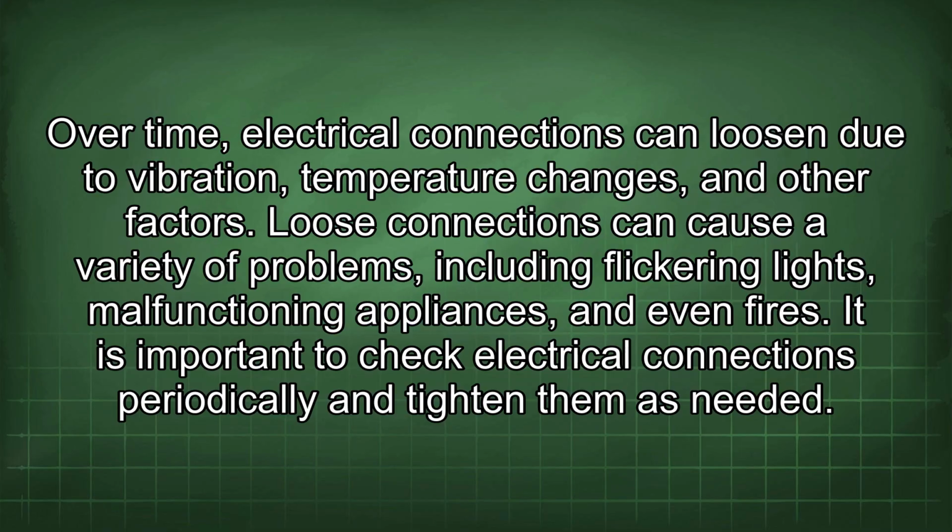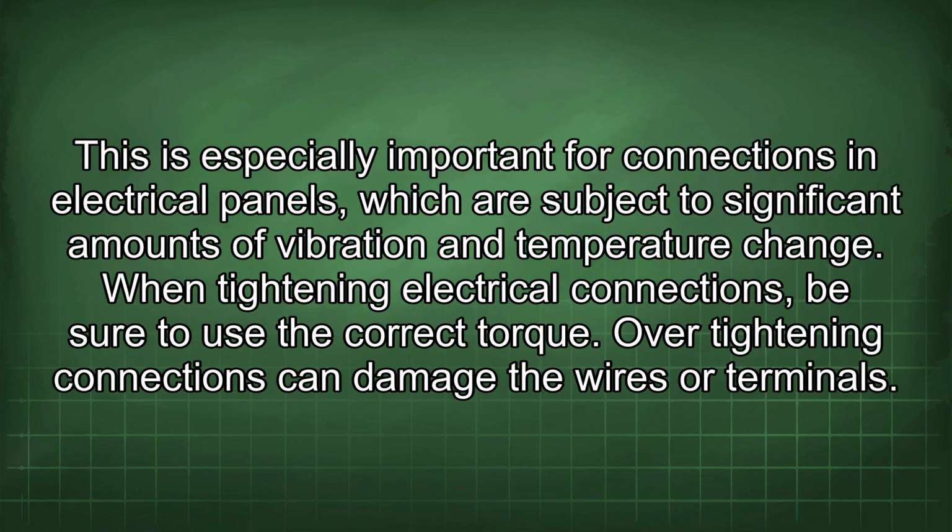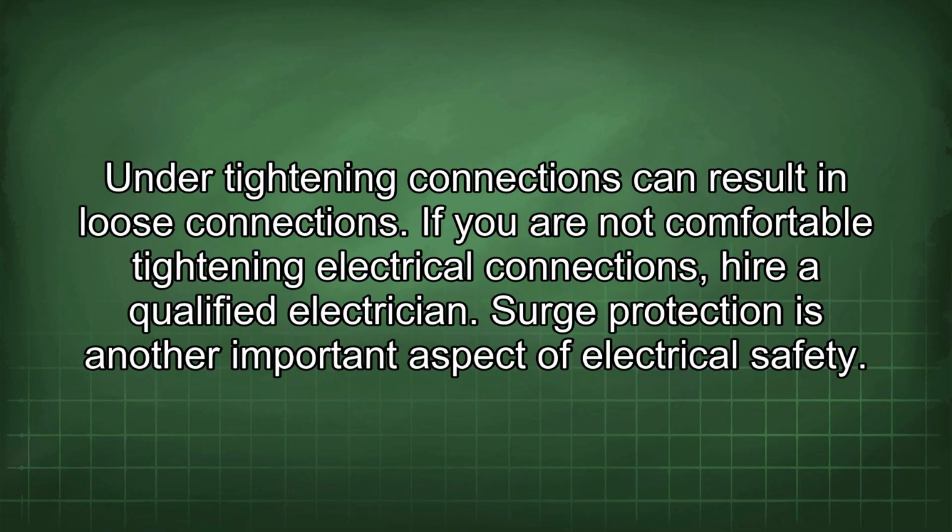It is important to check electrical connections periodically and tighten them as needed. This is especially important for connections in electrical panels, which are subject to significant amounts of vibration and temperature change. When tightening electrical connections, be sure to use the correct torque. Over-tightening connections can damage the wires or terminals. Under-tightening connections can result in loose connections. If you are not comfortable tightening electrical connections, hire a qualified electrician.